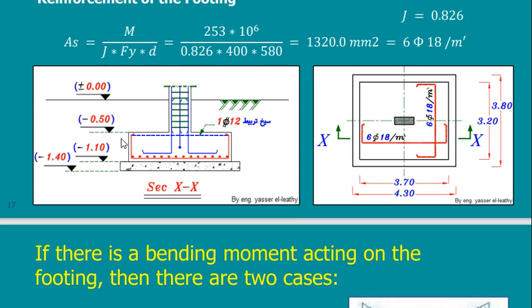That's why isolated footings are very economic. I don't have to put top reinforcement. And of course I put the reinforcement of the column, not the reinforcement, just we call it in Arabic ashayr, the starters of the column.